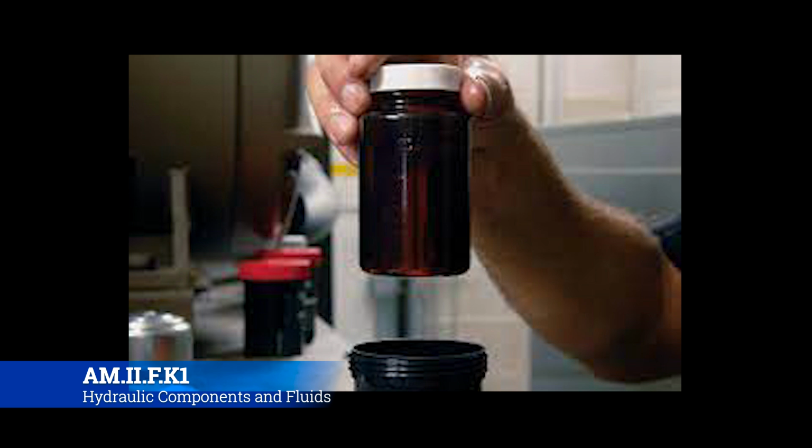So one of the things that you're going to continuously do is contamination checks. Now this can look very different on different aircraft and different maintenance programs, but a sample system like you see here, where the guy's taking hydraulic fluid and putting it in a jar and he's about to ship it off to a lab, is very common. You'll see this happen with engine oil too, whenever we get to that in powerplant. But anyways, they're going to check and make sure that it's the right hydraulic fluid, and that it doesn't have any contaminants.